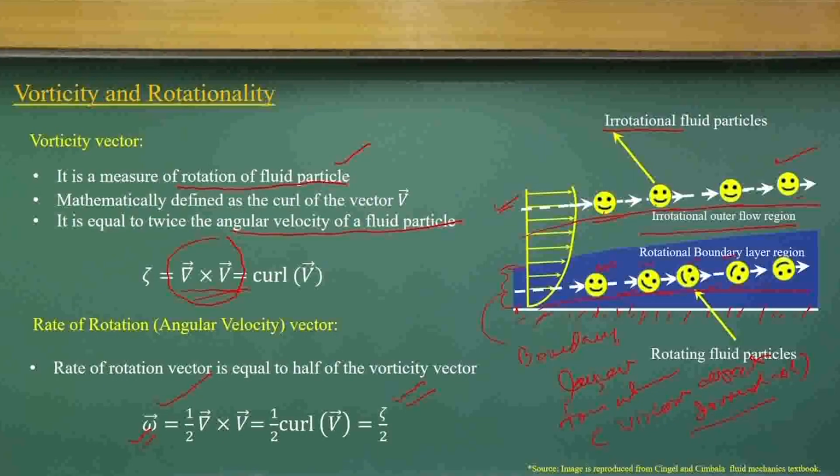So, that is what we measure in terms of vorticity. Please do not get confused between the vorticity and the angular vector. Vorticity is easy to define: it is the cross product between the del operator and V, whereas angular rotation is half of that. People who are not looking at angular rotations look at how vortex formations happen, so they talk at the vorticity level, not at the rotations level.